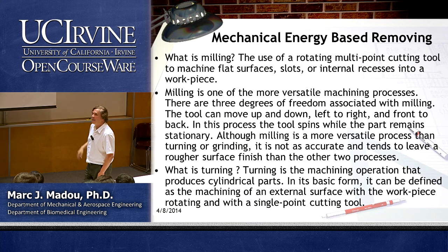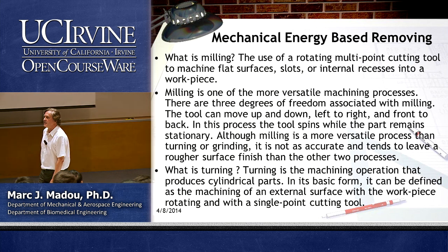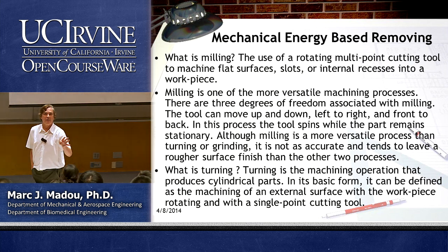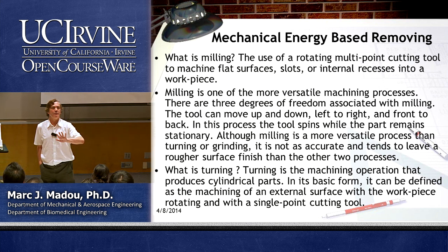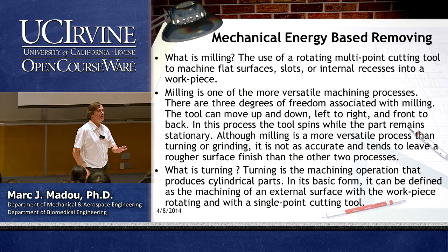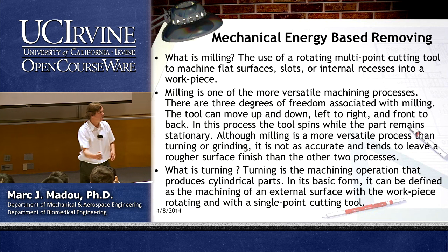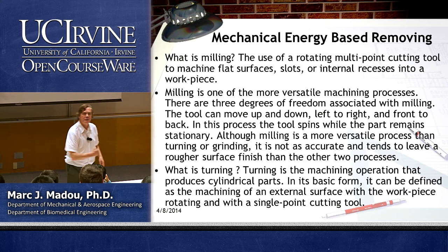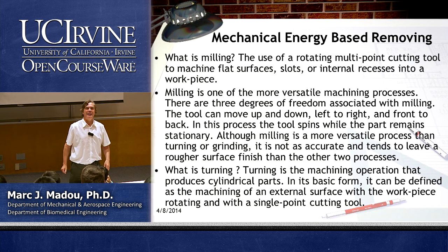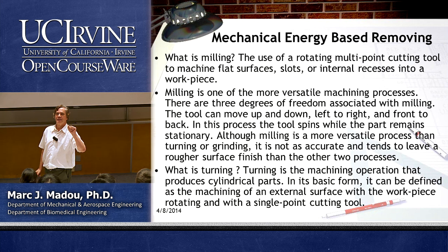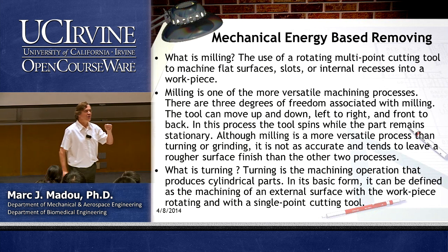Now, when you're going to buy a CNC machine, it's going to be a 3-axis, 4-axis, or 5-axis. I wonder if someone would already have the foresight. There is no 6-axis machine. So think about it, right? This way, this way, and then rotating around this axis. That will only lead to 5, not 6. If you don't understand it yet, I'll have a drawing a little bit later.